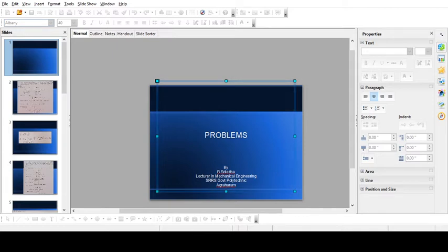Now the outer diameter suffered a compression of 0.00032 mm. Now we need to calculate the Poisson's ratio. Mu is nothing but lateral strain by longitudinal strain. Next, Young's modulus, it is stress by strain, and shear modulus and bulk modulus. So we are going to make use of the relations between all the elastic constants for this particular problem.